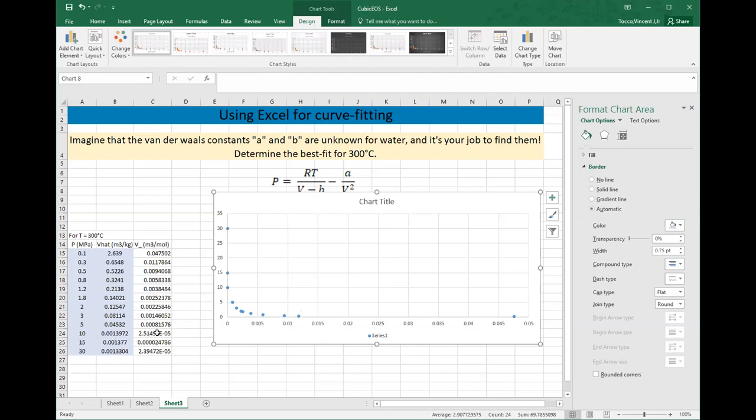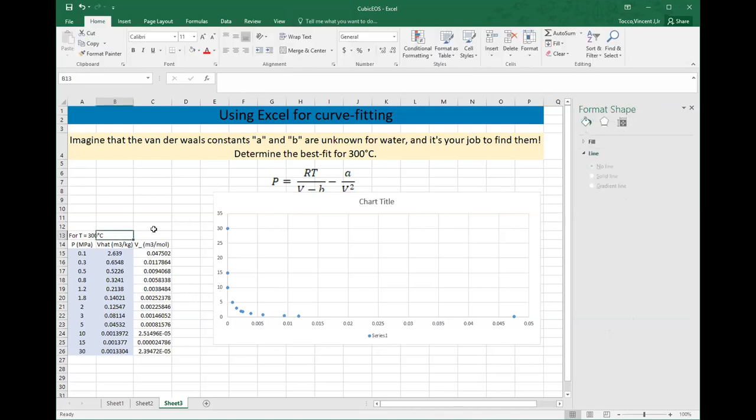And then the other pressures have this kind of 1 over X type of fit to them. So the saturation pressure is probably somewhere between 5 and 10 megapascals just by looking at the plot. And by actually looking in the steam tables, the saturation pressure is around 8.5 megapascals. So that makes sense. This is the jump between the superheated vapor state and the subcooled liquid state.